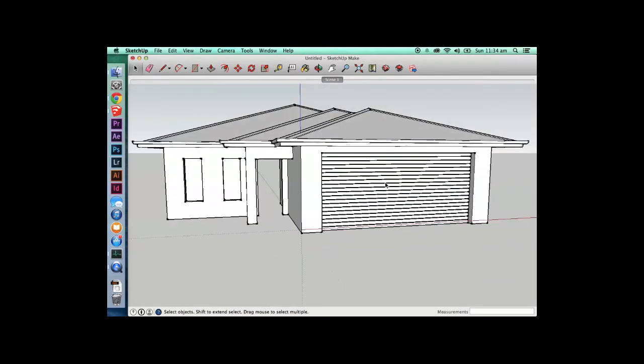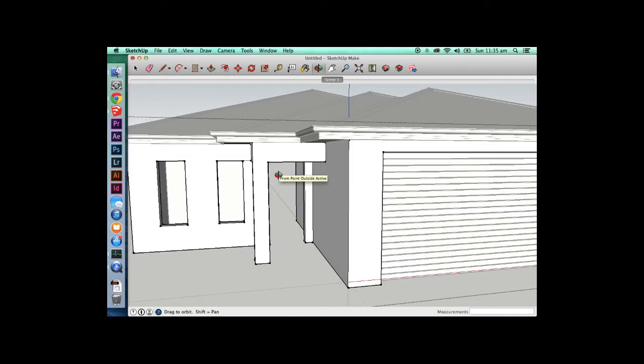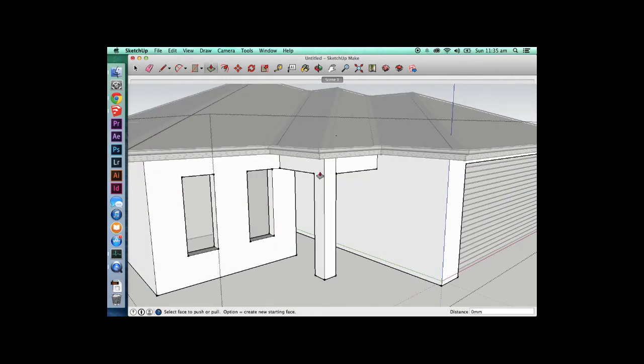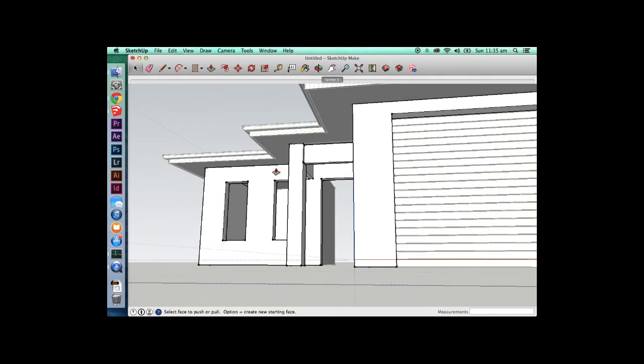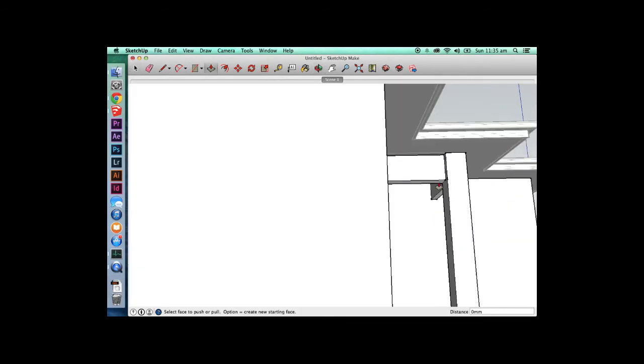Now for our garage door, I'm going to do a common trick just to make houses look a little bit nicer, give them a little bit more shadow lines around the place. I'm actually going to make these bond beams, offset back in 100 mil. Keep it accurate, I'm actually going to bring in 100 mil this way again, because they are 200 millimeters wide, not 100.